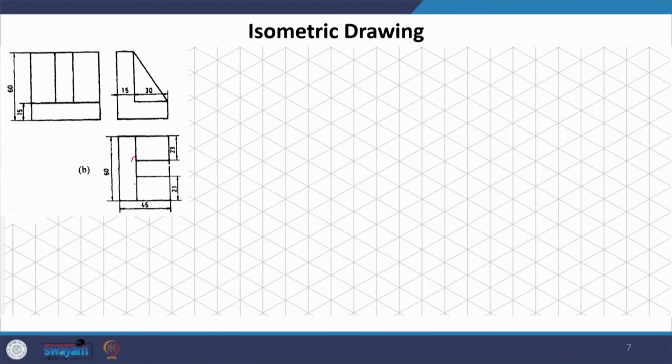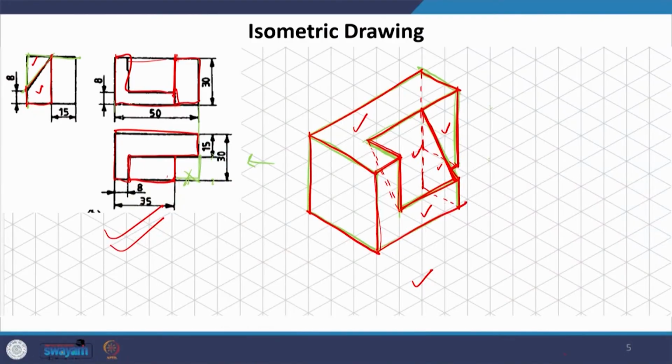Remember that no line should be left from the drawing. If there is a line, it must be seen. Now, if there is a continuous surface, you will not see a line. Just as in this case, since there was a continuous surface, we cannot have a line here. No, it is not going to come. The lines will only come when there is an edge.